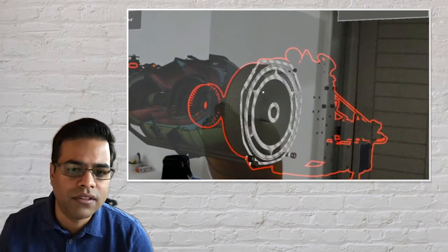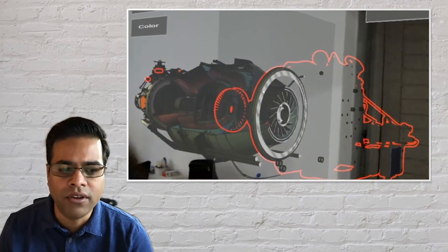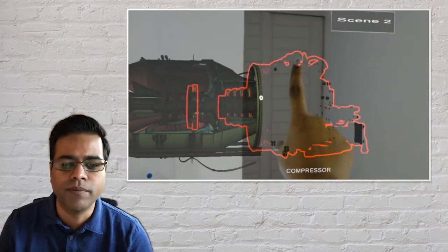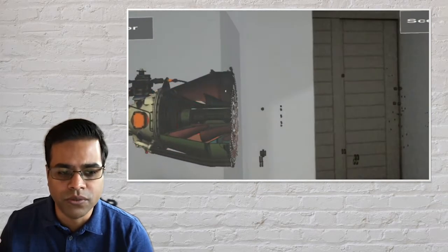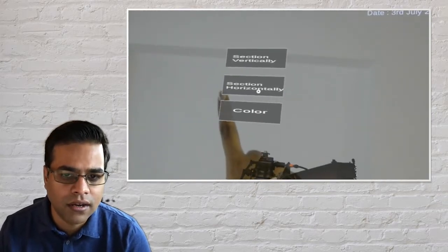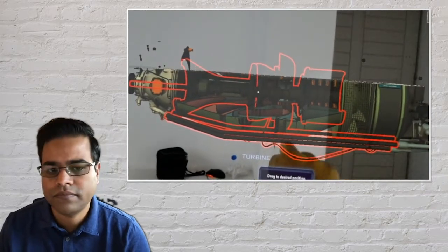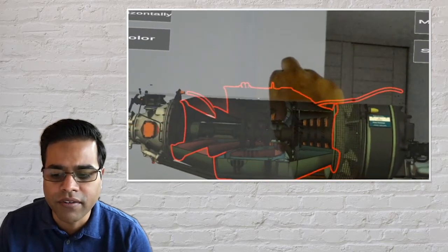You can make rapid iterations now, because you don't have to decimate and bring down the polygon content as you're changing your CAD model. You can iterate very fast, from changing the CAD model to bringing it down into the HoloLens directly from the server. So the server that you're using to render your CAD can actually be used to render out onto the HoloLens with basically the same GPU capability as a high-end desktop PC. So this is for just purely rendering.